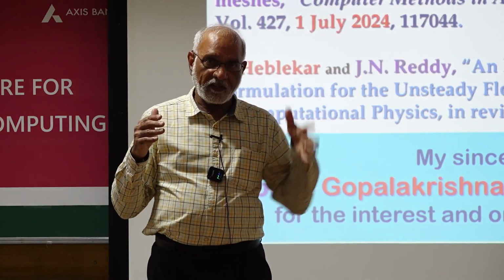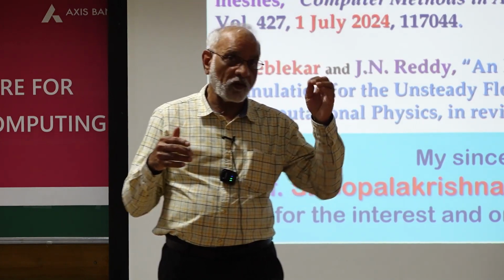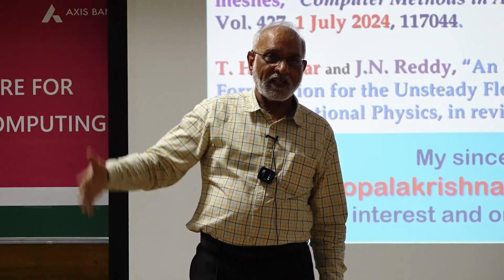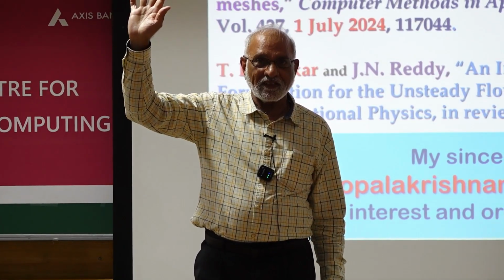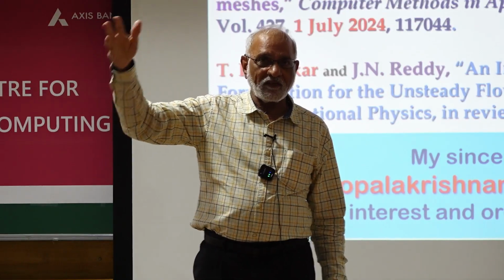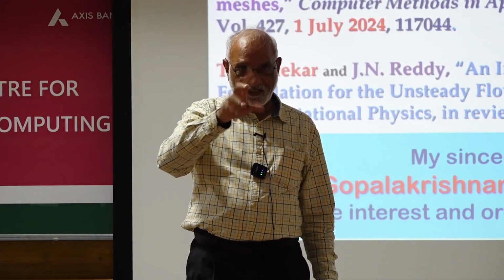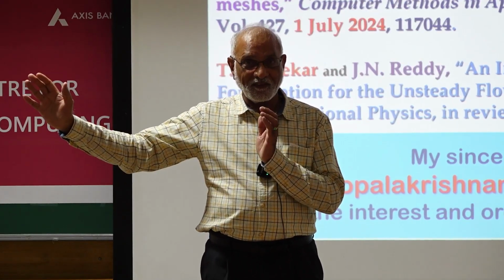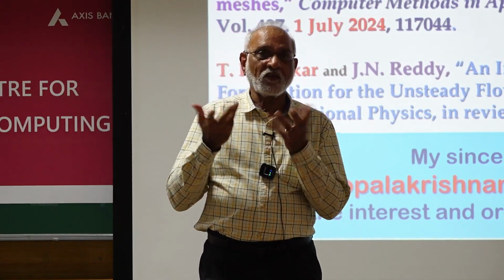Okay. So the inflow is of course specified velocity. In this case, we use a uniform one. If you want to put fully developed flow as input, that is okay too. The outflow is stress-free. So that means I don't specify velocities. Stress-free means that gradients are 0 because it's fully developed. So that dictates that you have to be far away from the cylinder to realize that. The physics dictates that. If you're too close to it, it won't be free.